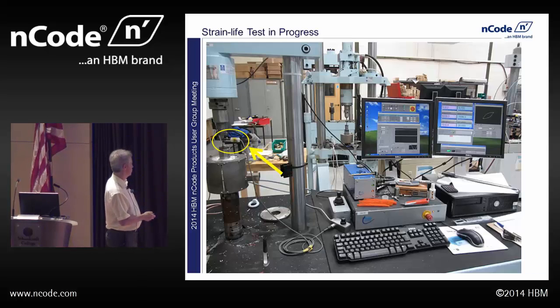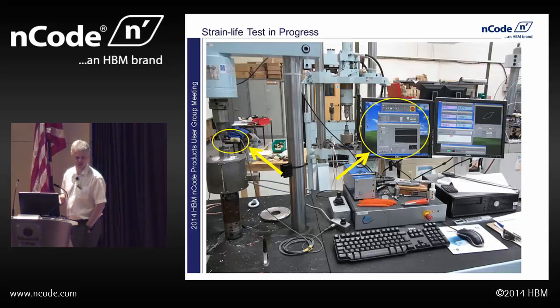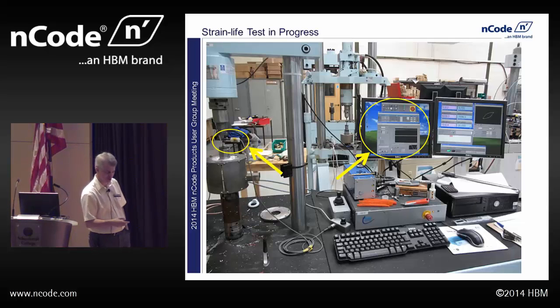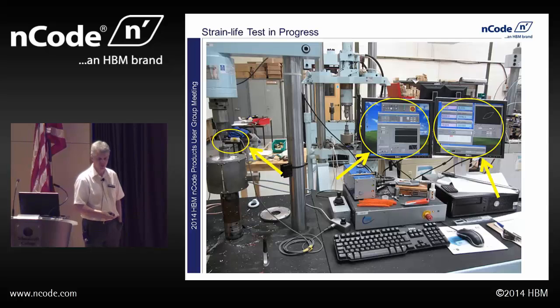So there you've got a just about visible test specimen, the smallest bit on the left, with the extensometer attached, and then a pseudo old analog test interface, now in digital form, but I guess it makes the test engineers feel okay. There's rigs we used to use before in terms of analog, we've now got a digital version of it. So all the control is on that screen, and then all the feedback and analysis on the second screen. So there you've got hysteresis loops coming out directly, feedback data, checking the test as it's going through.